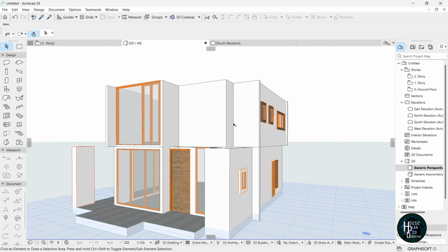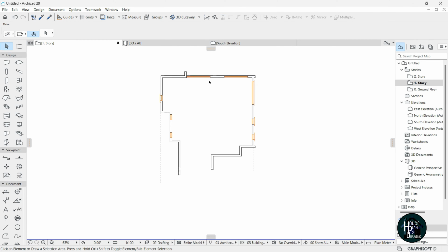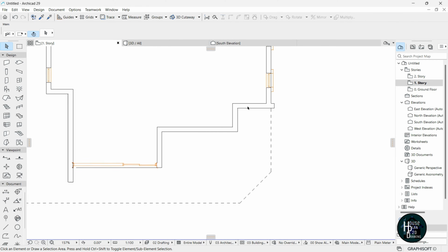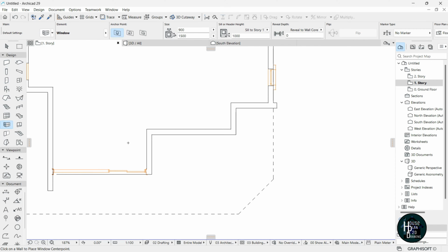So there's going to be a corner window here. So what we want to do is just go to, and we're going to add that real quick. It's supposed to be somewhere around here, so we're just going to look for a corner window. This is it right here under the design tab. You want to click this, then come here and just click OK, and that's going to sort itself out.